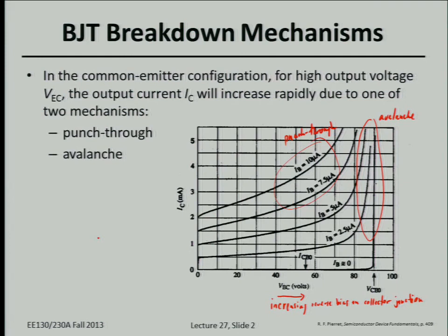Okay, so the question is, can you design an individual transistor that can withstand high voltage? Yes, sure. You just have to make the base width wide enough and the doping levels reasonable to withstand that. In fact, there are whole textbooks written on how to design BJTs for different applications. If it's for switching applications or amplification